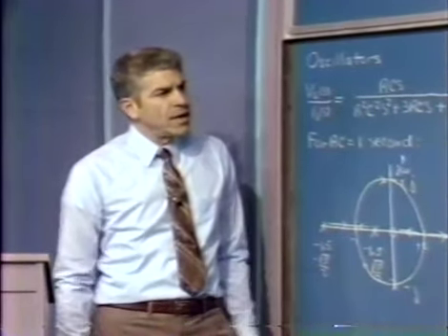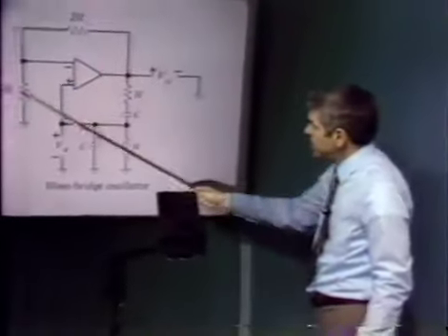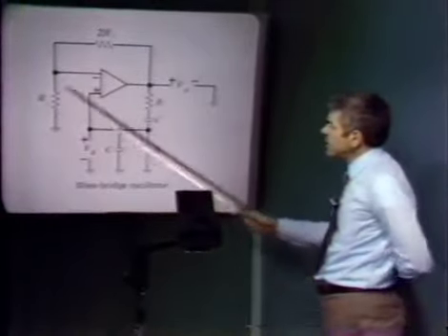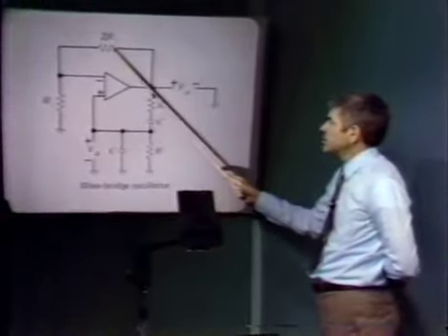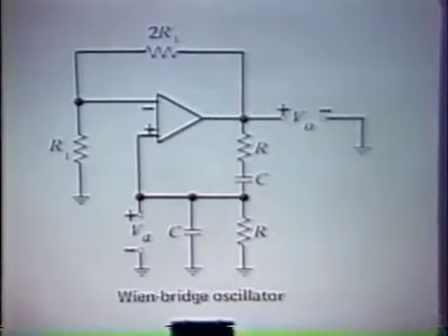And at least one possibility is to modify our amplifier a little bit. As shown, our amplifier provides a gain of +3. However, we could make the feedback resistor, for example, nonlinear, such that for small signals we got a gain of 3, and for larger signals we got a somewhat reduced gain.